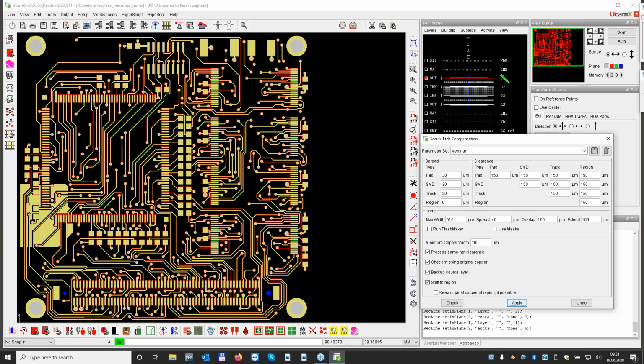Or you can say, with this technology I don't need to make only boards with 200 micron clearance. I can also make boards with maybe 100 micron, and use this to free up space wherever I need it. We can also talk about 80 microns, and then maybe go down to 70 microns.